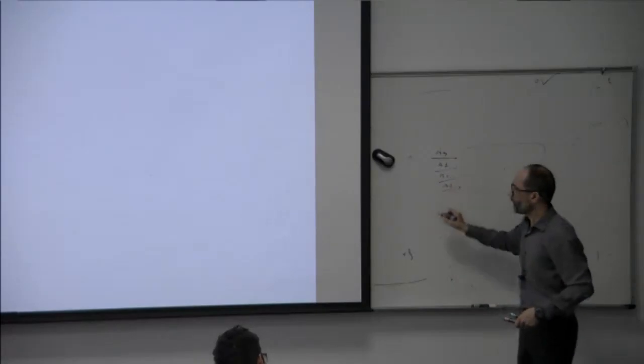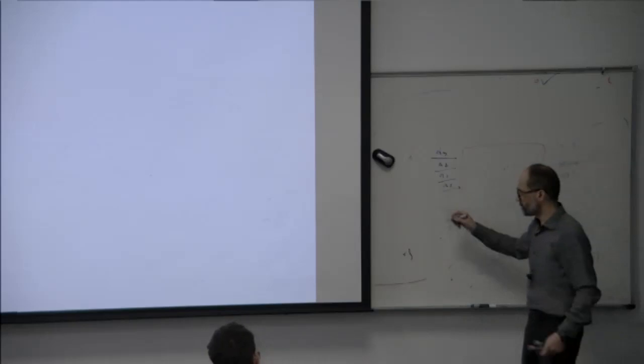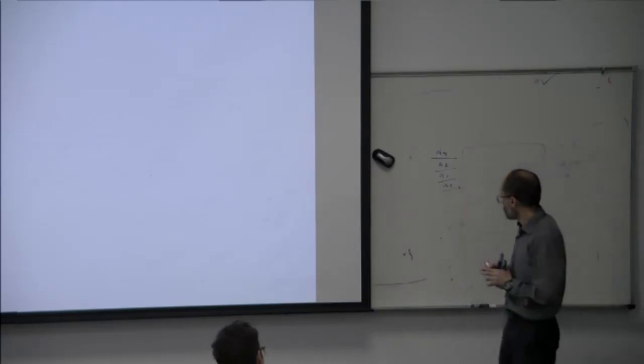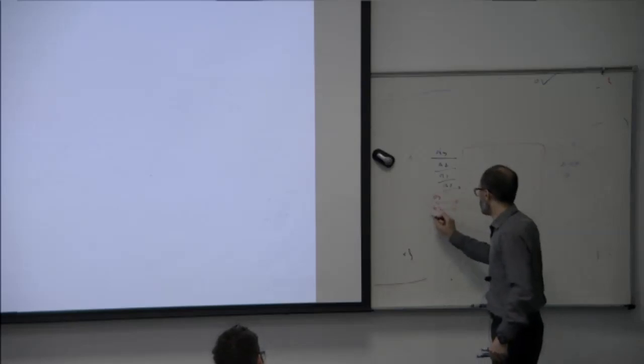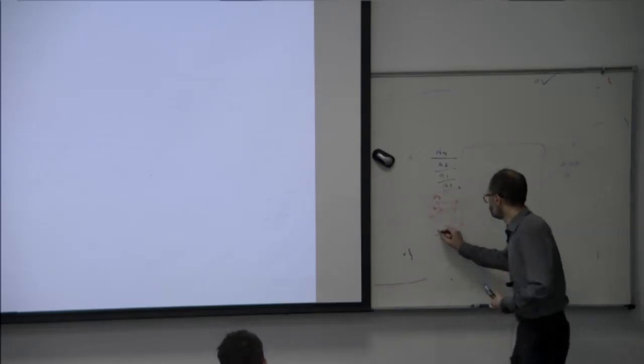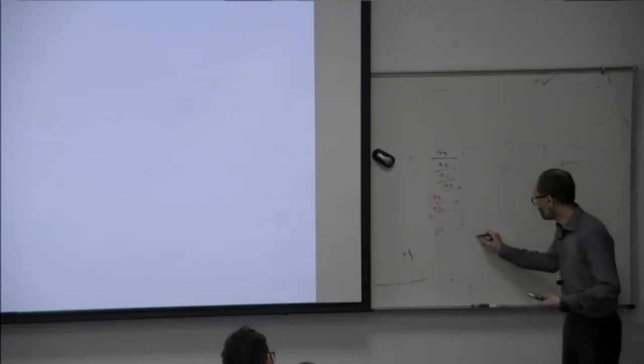A3, A2, A1, A0, because I want A plus B. A is 4-bit data, B is 4-bit data. What should be the other input? Yes, please help me: B3, B2, B1, and B0. And we also have another input, which we call C in. This is the carry in. Okay, now this is A plus B.